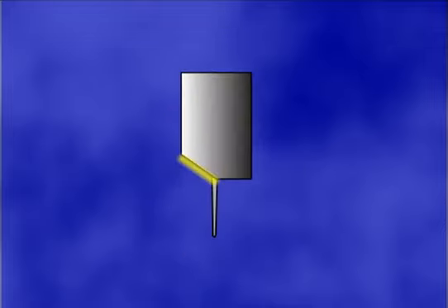An angle cut into the slide on the air cleaner side increases air velocity at low throttle openings. The increased air velocity decreases the air pressure in the venturi, allowing more fuel to enter the carburetor. The height of the cutaway portion determines the amount of air entering the venturi. The larger the cutaway, the leaner the air-fuel mixture.